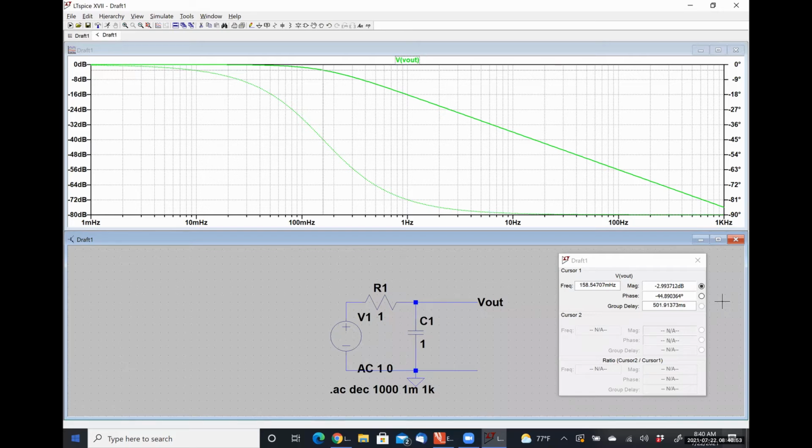So this is another place where LTspice, operating in degrees effectively and in linear frequencies, is going to make it slightly different than our analysis, where we're used to working in angular frequencies involving radians and all that kind of stuff. But it's all the same. It's just looking at it from a slightly different perspective.